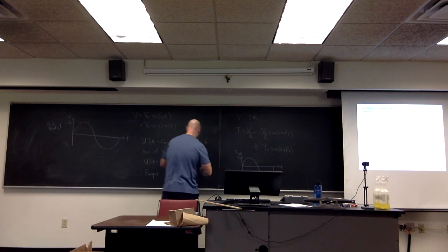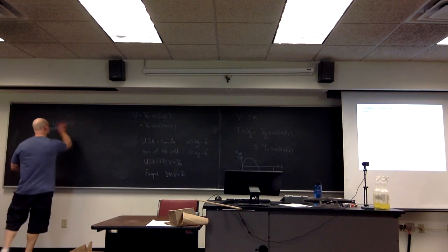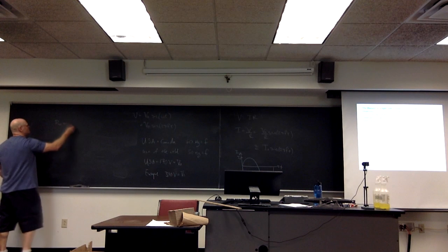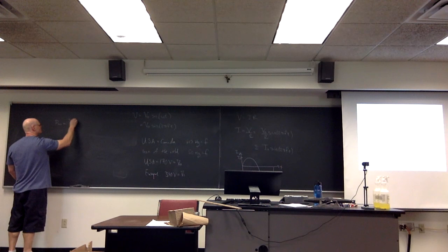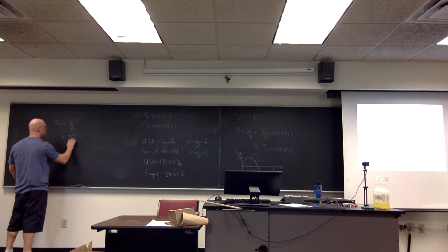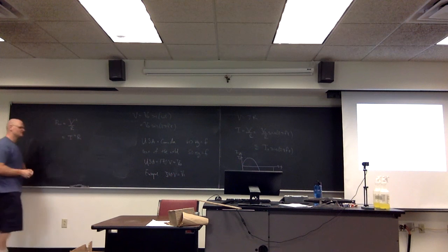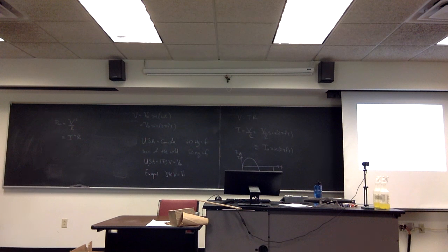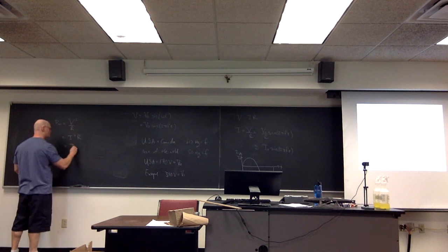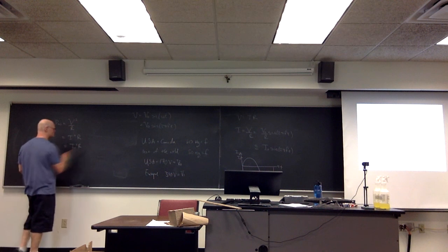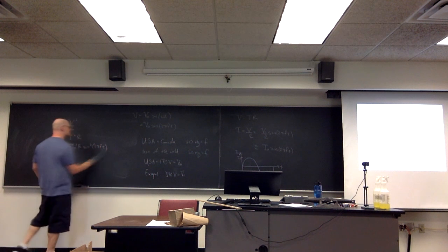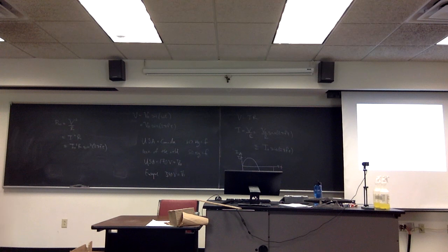If I'm trying to transmit energy via a transmission wire, for example, we're going to have a power loss, which we now know is equal to either the potential squared divided by the resistance, or the current squared times the resistance. Either one of these is fine. If I use the second quantity, this is equal to the peak current squared times the resistance times sine squared of 2 pi times the frequency times the time. So this is my amount of power which is being lost.